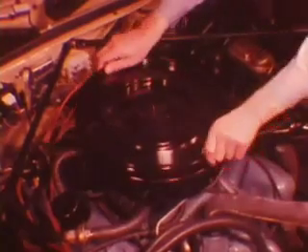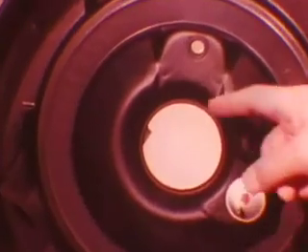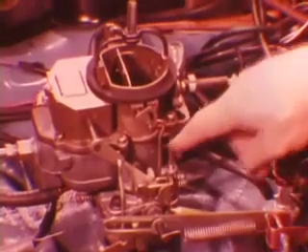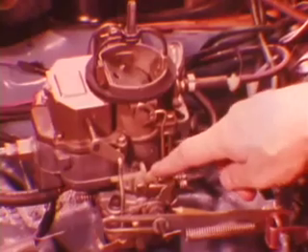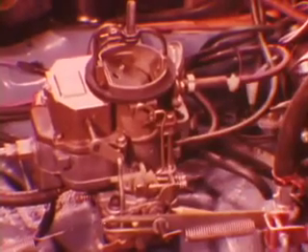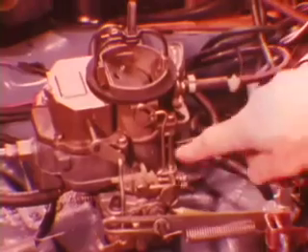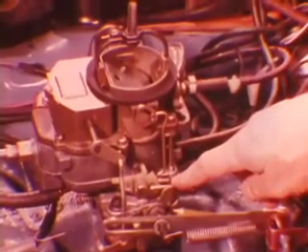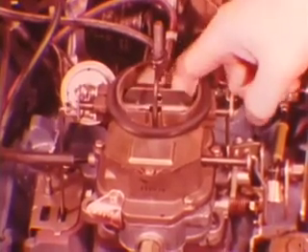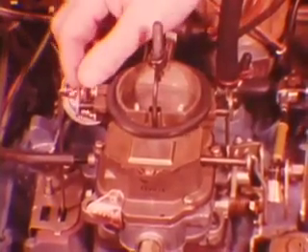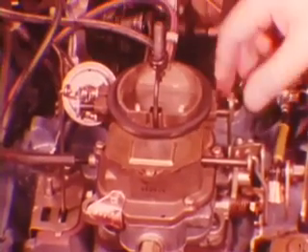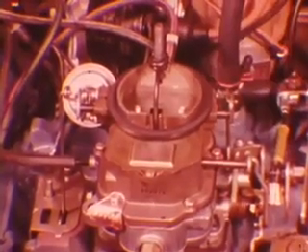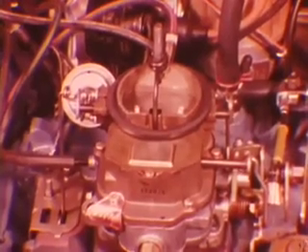If spark is okay, remove the air cleaner cover and see if the choke is closed. Notice that the air cleaner on some models locates with a tab. The closing force of the choke spring positions the fast idle cam, which in turn holds the throttle valves open a proportionate amount. Incorrect throttle opening affects the mixture, which can cause hard starting. While the engine is cold, snap the choke valve shut a few times to check for sticking. Binding anywhere in the choke linkage that affects choke valve and fast idle cam positions will cause hard starting.